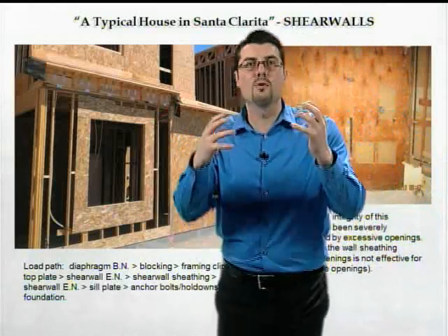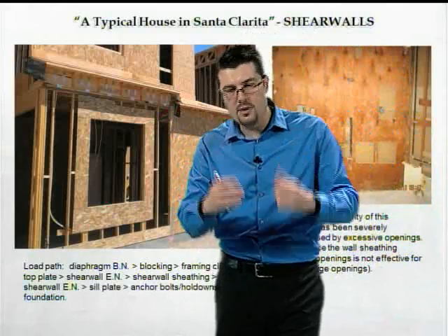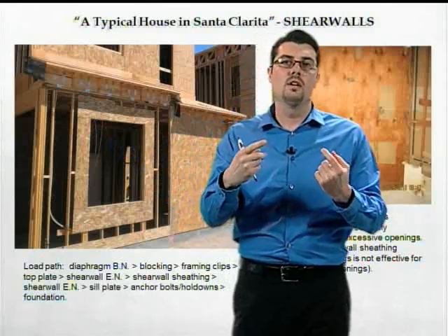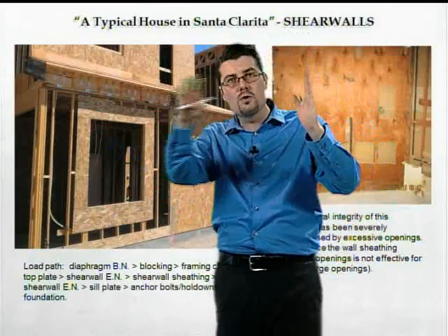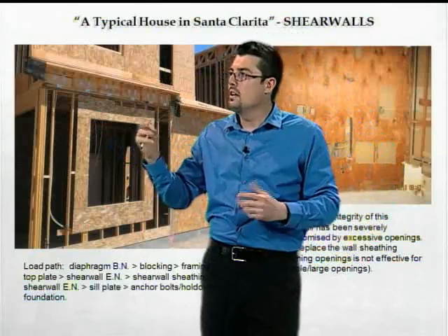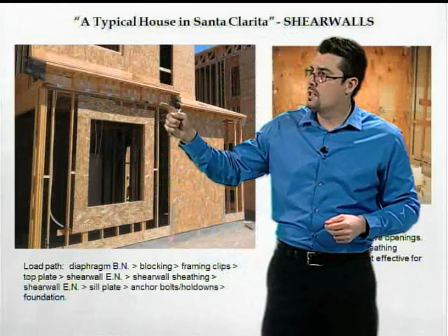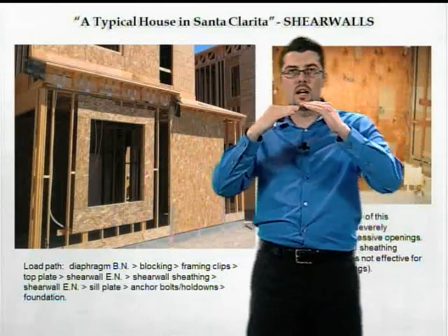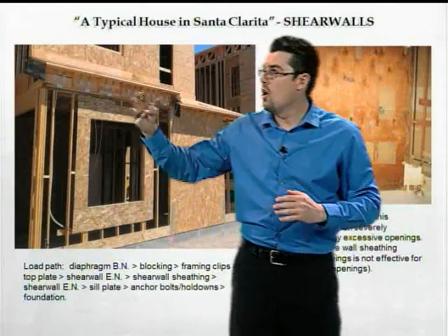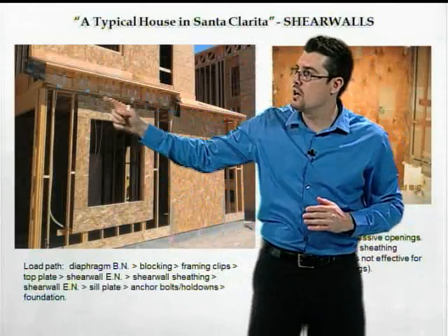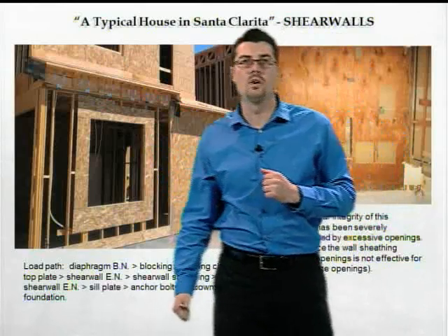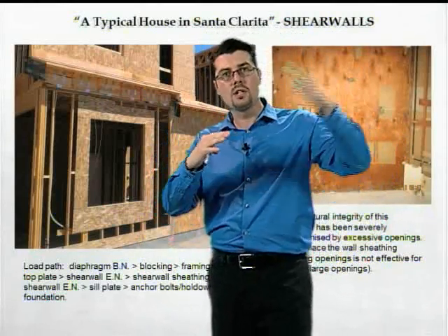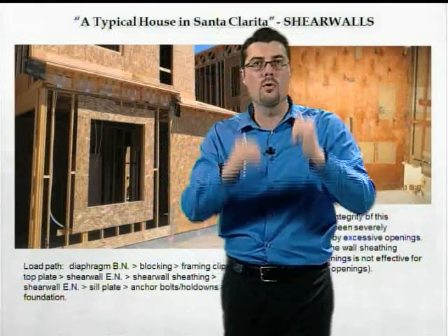So conceptually, that's what I'm trying to convey to you today, so when you look at a structure, you can see that behavior. You can see the force transfer and understand. Now, if the top plate was cut right here, and there was not an adequate splice, all the force from this part of the structure has no load path to get to the shear wall. And so this is why top plate splices, those connections we were talking about earlier, are so important.